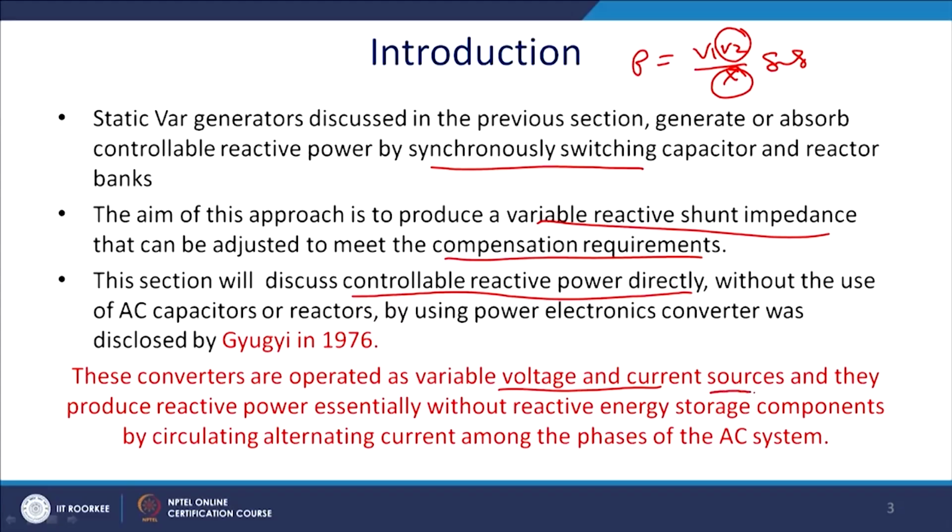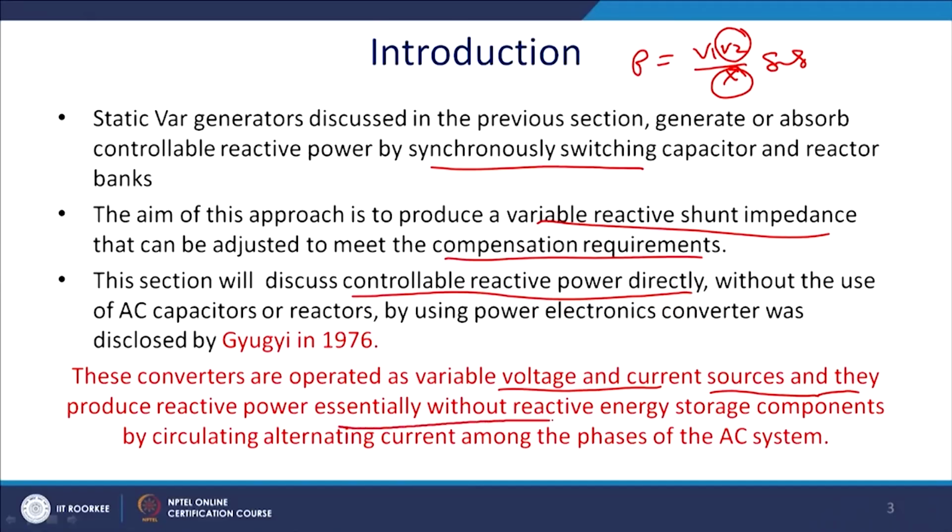Voltage source, current controlled inverters produce reactive power essentially without any storage of reactive elements. So, inductor and capacitor will not be there, which is one of the basic advantages of this STATCOM, essentially without effective energy storage components, by circulating alternating current along the phase of the AC system. So, it will be dynamically controlled and faster in action than the SVC,